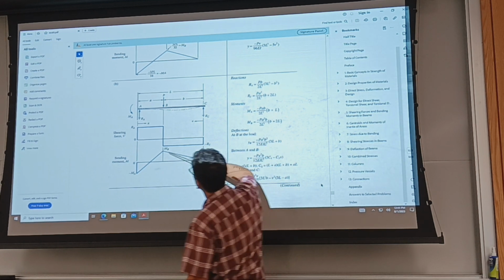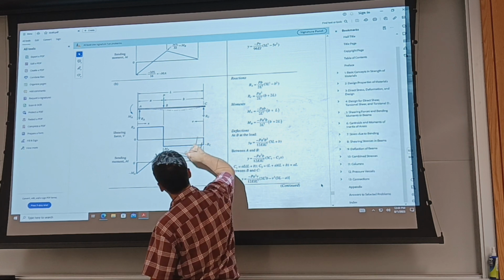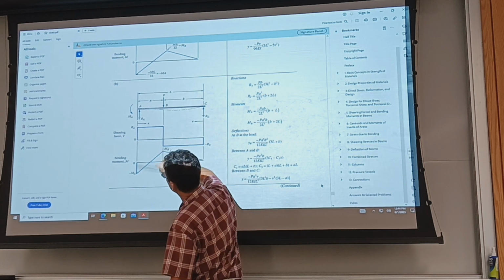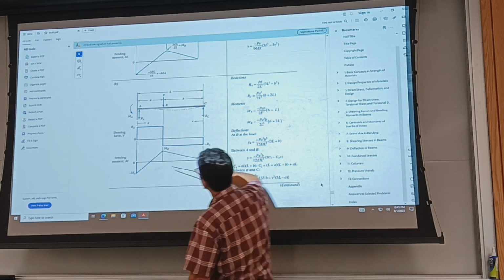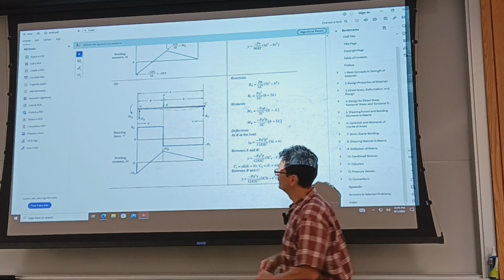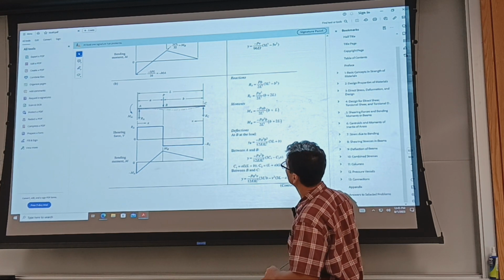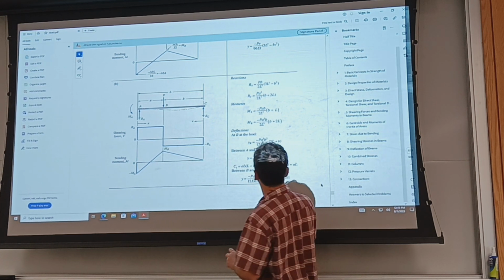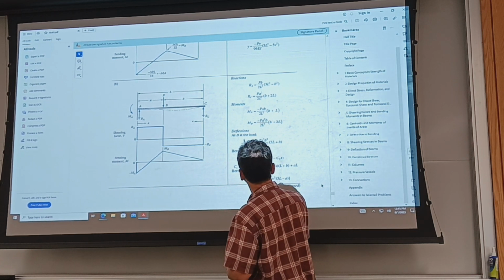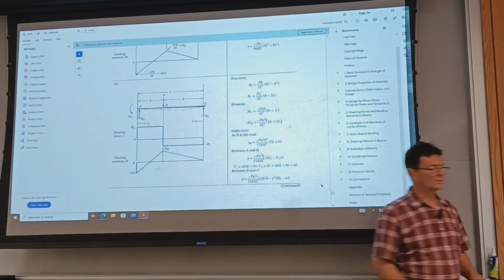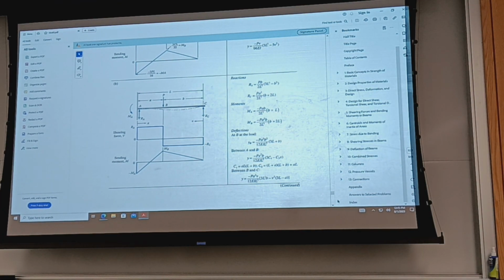And then it shows, readily available, what the maximum moment will be, which could be less than this one, at where shear goes through 0. Okay, and deflections at the loads between A and B equation. So this is specific to location. This is a function of y, and likewise a function of y between B and C, the rest of the beam.